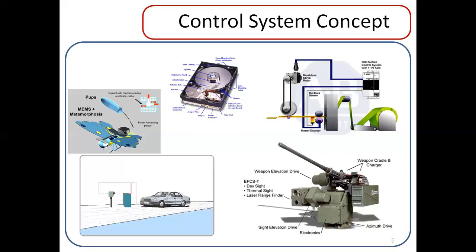and that signal will be fed back to the processor or else the controller, and it will compare it with the reference signal given in the set of instructions as per the program. So initially in the input signal given to the system, the actuator which is connected to the gate should be opened to 90 degrees. So whether it has been opened to 90 degrees or not, after the motor orientation to 90 degrees, a sensor will be highlighting, and it gives the feedback to the controller that the 90 degrees orientation has been done. In the case of open loop, this process will not exist. So that is the basic difference between the open loop control system and closed loop control system.